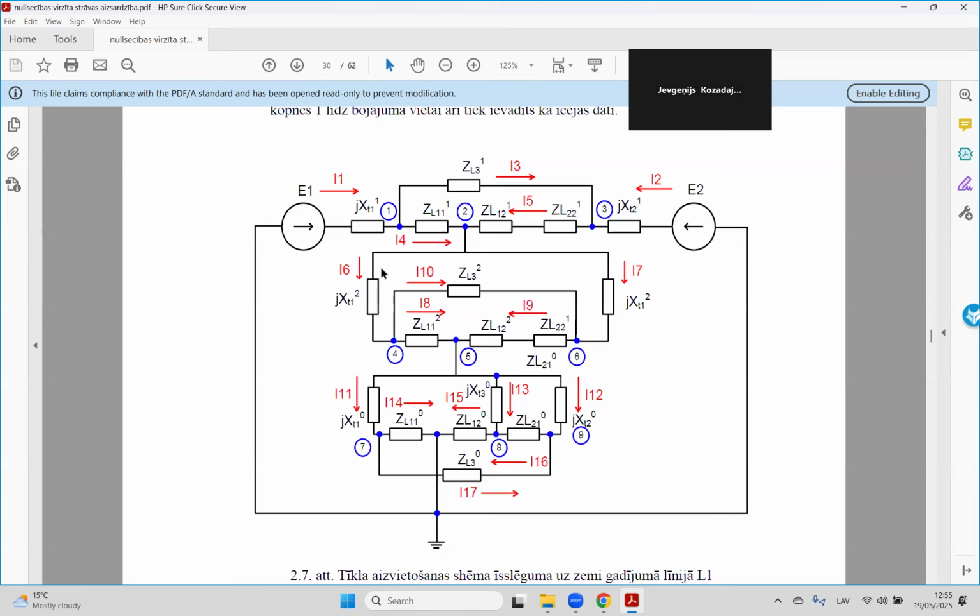One remark, very important. We have different types of fault: symmetrical fault and asymmetrical fault. If we have a 3-phase fault, we have a symmetrical fault, and this is the simplest scenario, because we just need the positive sequence equivalent scheme. We just represent the transformer with impedance, the line with impedance, the generator with impedance, to construct an equivalent scheme and calculate, nothing special.